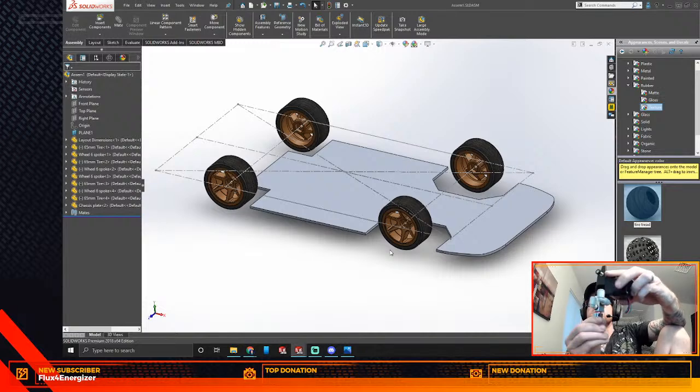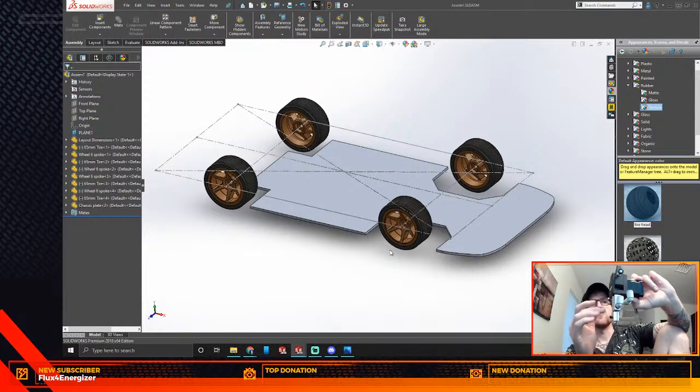So if you're into 3D printing and having a heated enclosure, if you have an air-cooled heat break zone, all you're going to be doing is throwing that hot ambient air towards that heat break, and you're going to have heat creep go up. And when you have that heat creep go up, it's going to potentially jam the filament inside your heat break zone, cool zone.